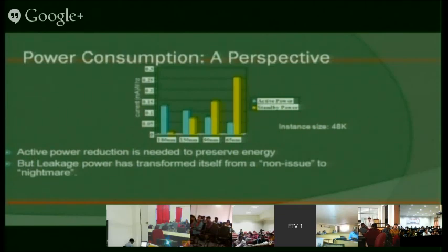So this is at 180 nanometer. If you reduce the technology node and go to 130 nanometer, you can see the blue has decreased some, but see the increase in the yellow. You see at 90 nanometer, the standby power is around 50-60% more than the active power.